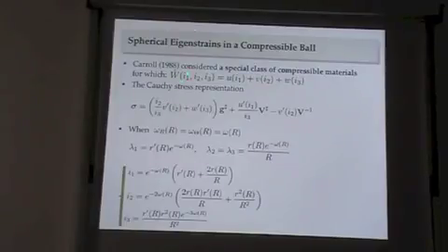W is a function of I1, I2, I3, and I'm going to look at this special class with this additive property, that this function is some arbitrary function of I1 plus I2 plus I3. Then the Cauchy stress representation would look like this. This is the special class that I'm going to be looking at.